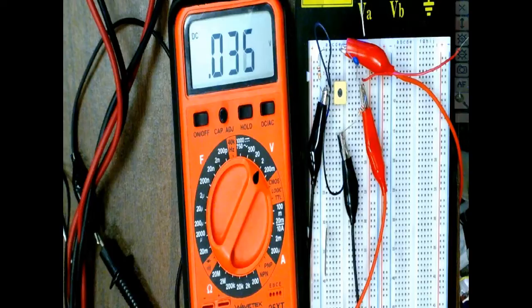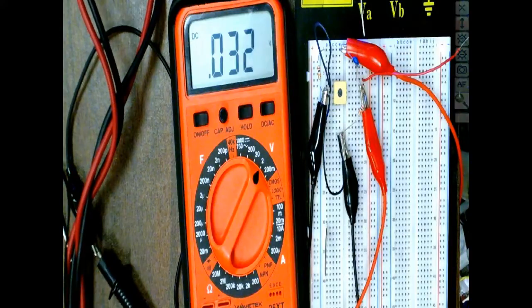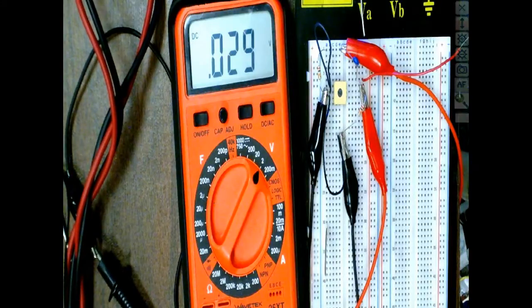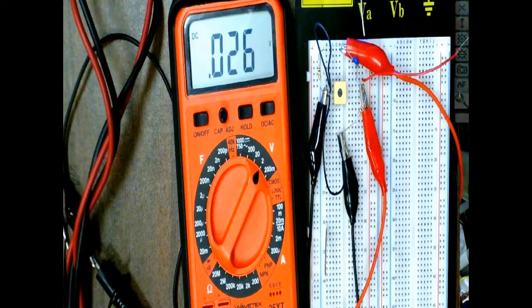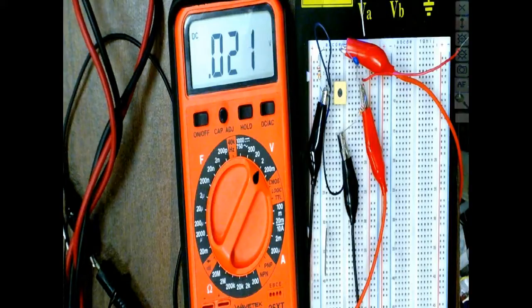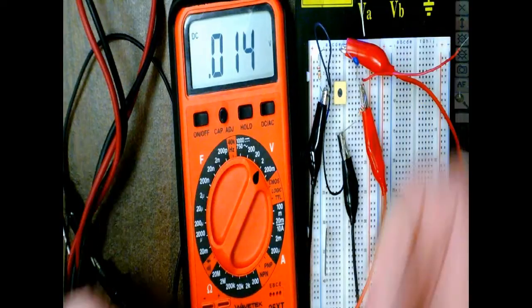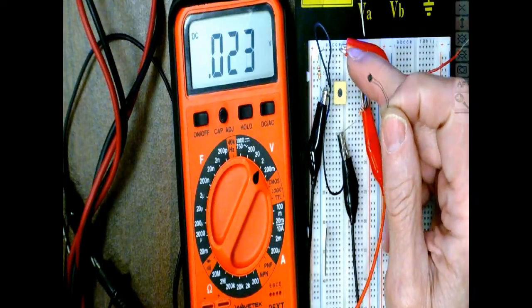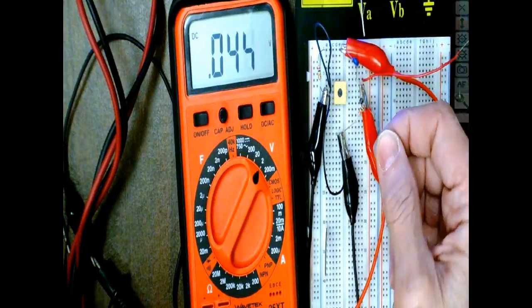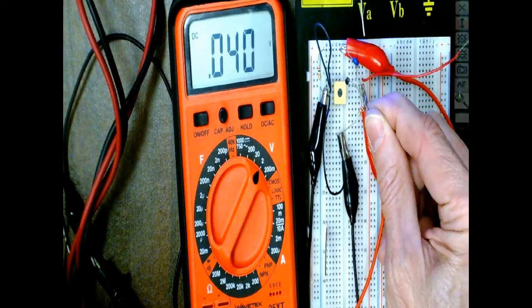You probably can't get those locally, but you definitely can get them online if you wanted to set up a circuit that actually measured true temperature. And what you'd use is those integrated circuits. So this is basically a thermistor. So we got several types, and all ours are NTCs. So this is the one I originally had, and this guy here has about 10K at room temperature. This guy right here had about 100K at room temperature.